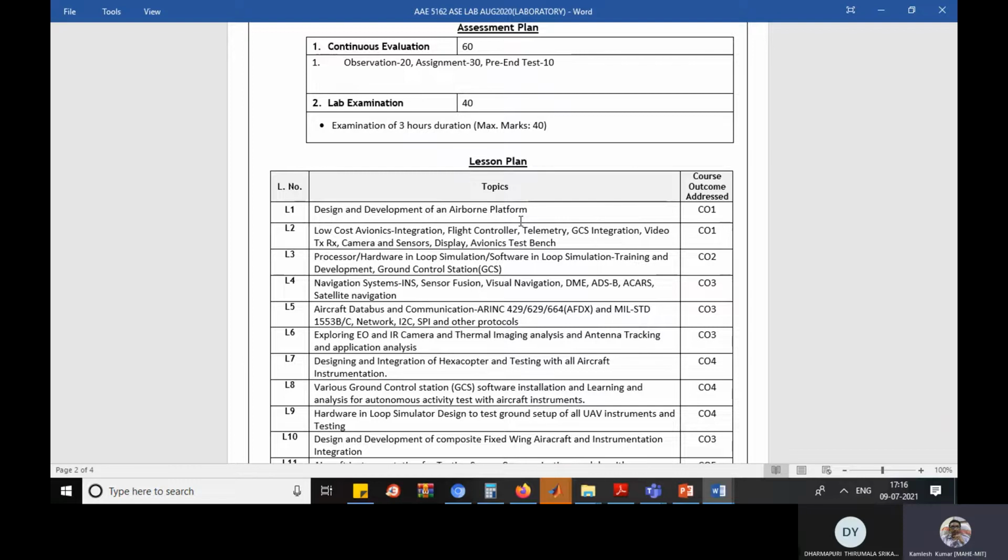So this is the first prototyping, where you can use the skeleton in terms of balsa ply, veneer, or maybe carbon tubes, and then you have monocoat over that. Okay, so you can have some coating as a skin, and that skin can use what is called monocoat materials. If you check that, you will find those materials available in the lab, and in the market also. You can check what those materials are.